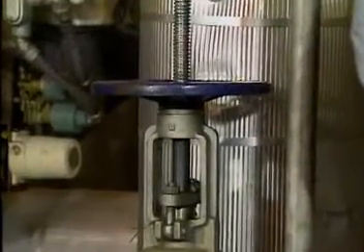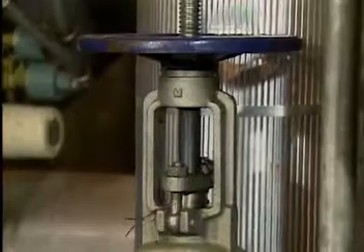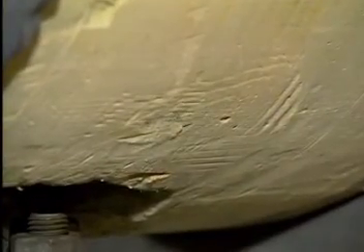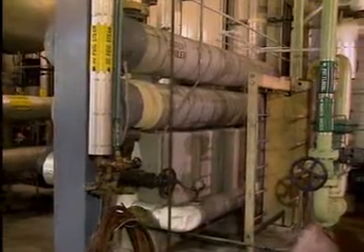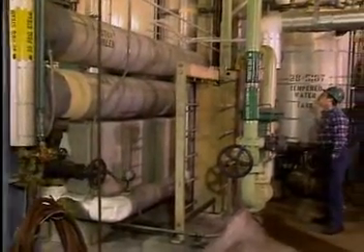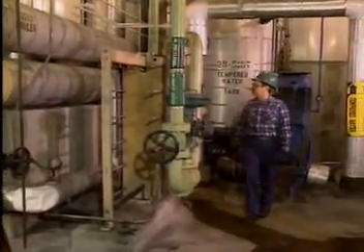Besides checking instrument readings, an operator should also check for leaks and for damaged or missing insulation. Problems such as these could affect the operation of the heat exchanger and pose hazards to personnel working in the area. In this topic, we looked at some basic procedures for the startup and shutdown of a typical shell and tube heat exchanger. We also looked at some operator responsibilities associated with operating a shell and tube heat exchanger.